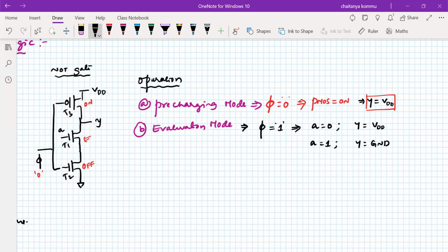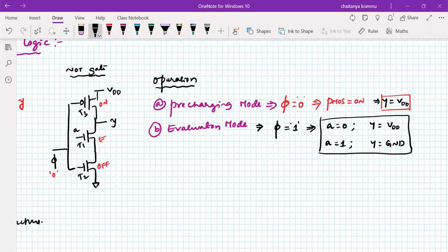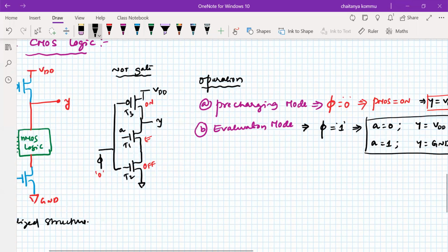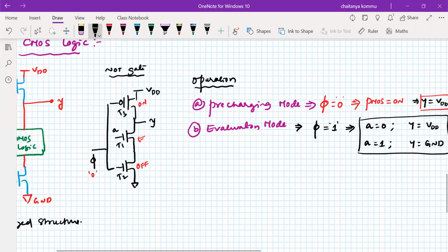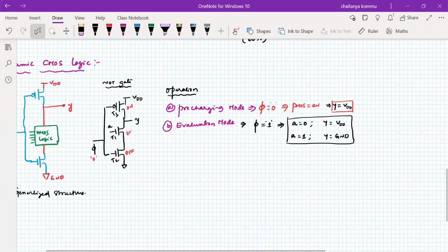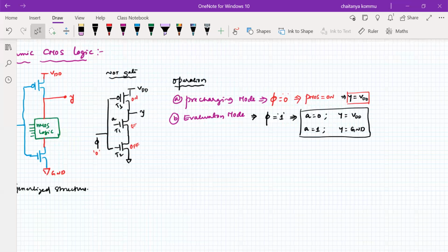Am I right? So this is what is important: this is the evaluation phase of the transistors. So far so good, but there is a problematic situation. It does not depend upon ratioed logic, because pull-up and pull-down are independent, depending upon the input signal. But the problem here is that it is not possible to cascade by a single clock.